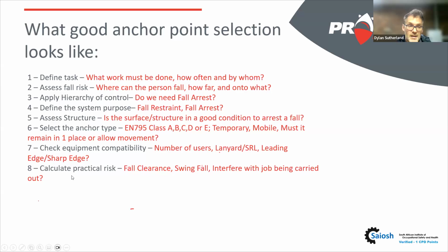Step 8, we need to then calculate the actual practical risk. So what is the fall clearance? What is the swing fall potential? Is it interfering with the job being carried out? Is it going to be used? Are we going to use the safety equipment?